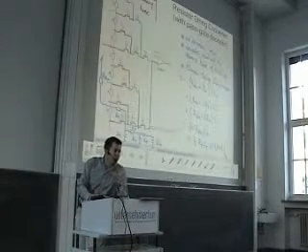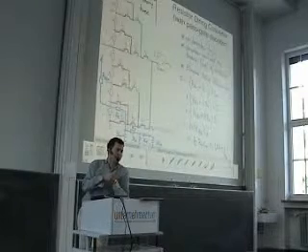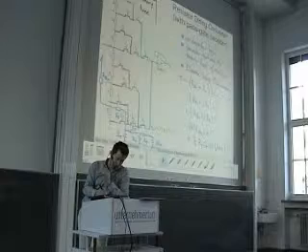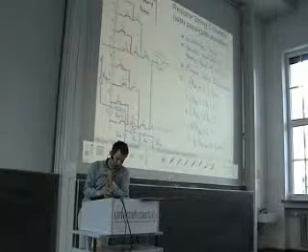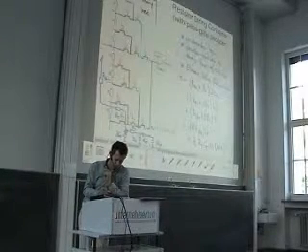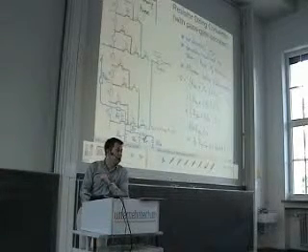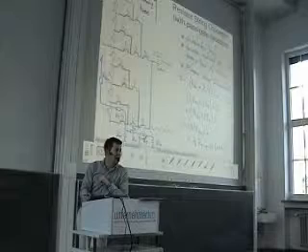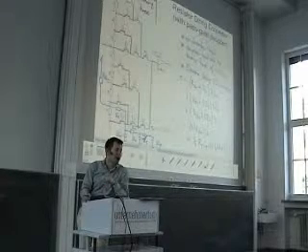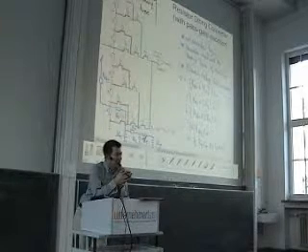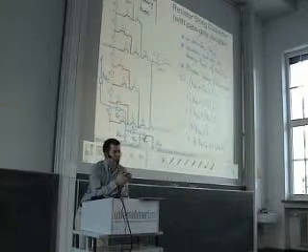So if we compare this to the resistor string converter, we can see in this case we have the problem that we have several switch transistors in series, which brings up our series resistance. So probably this one is the slower one. Well, this is actually not always true. It depends on the number of bits.